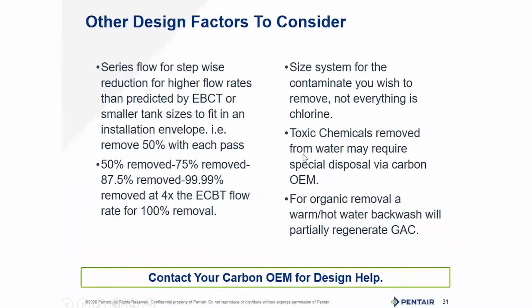Toxic chemicals removed from water may require special disposal via the carbon OEM. So if you're removing something especially nasty, you can't just throw this stuff in the garbage as a commercial operation. There are programs, check with your carbon OEM, where you can send it back to them and have it recycled or high temperature incinerated and disposed of.